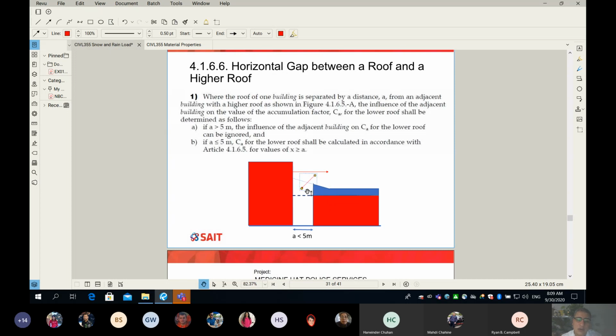This amount of snow will just fall to the ground. So how we do it, as I said, you just have to go through all the calculations, draw your snow diagram from 0 at the higher building, and then normal at XD, and then using the geometry, or trigonometry, of this, you are able to figure out this number.